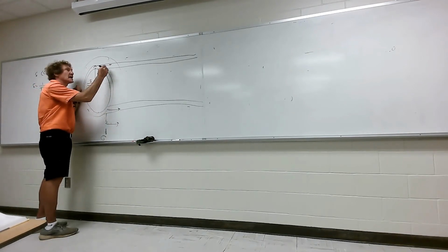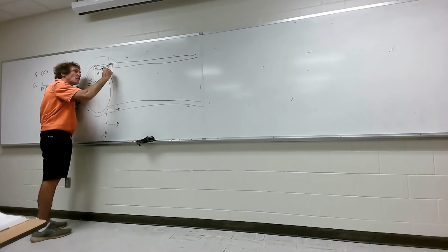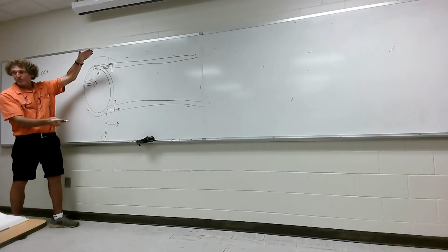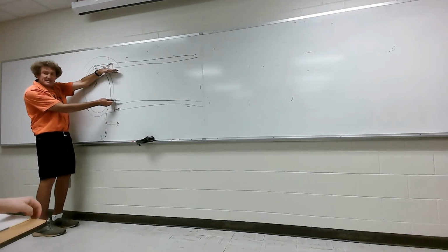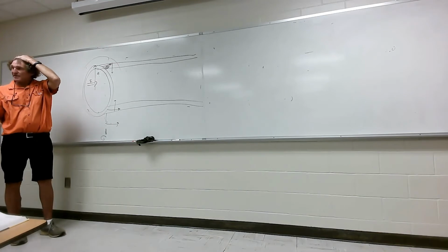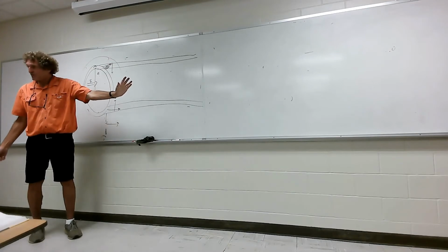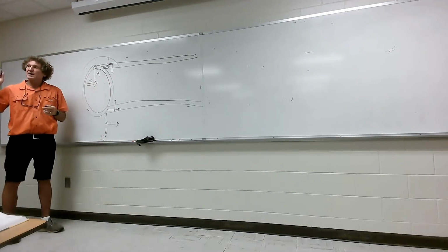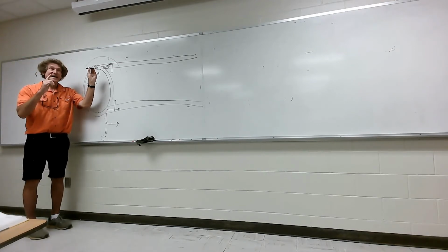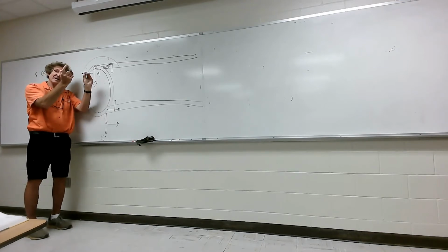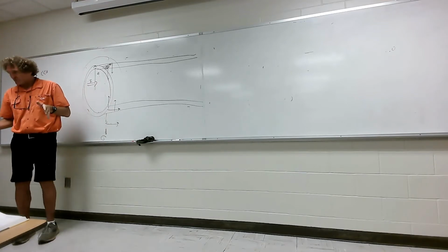That electric field actually decays very rapidly in here, and it causes currents to flow. The actual power flow in the wire is going from the outside inward. That means this power flow has a very small inward velocity, but it basically dissipates there. Now, the common way of thinking about DC is that we have current going this way, so the power flow must be going this way, but that's wrong. Because power, as you saw, is E cross H. If the E field is in this direction, and the H field is in the azimuthal direction, E cross H is into the center of the wire. That's the way the actual power is propagated.